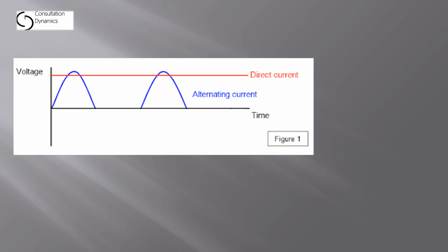Then as the power rises, the capacitor charges up, holds that charge until the next rise in power, and the next, and we effectively can convert the alternating current into direct current because we're ignoring half of the cycle and we're storing that electricity up within the capacitor itself. And that's how a diode functions.